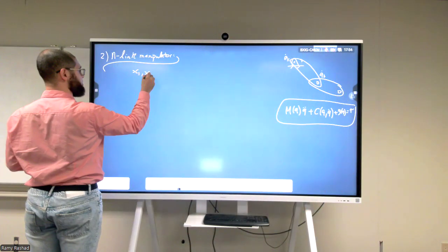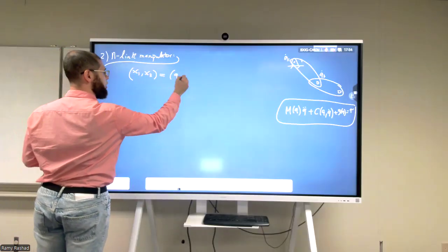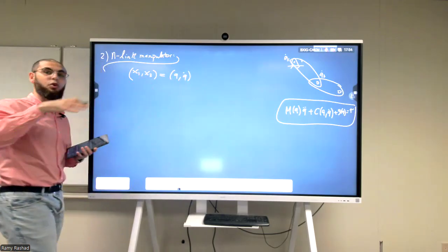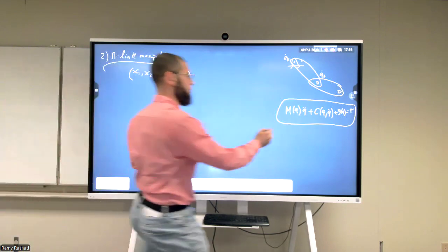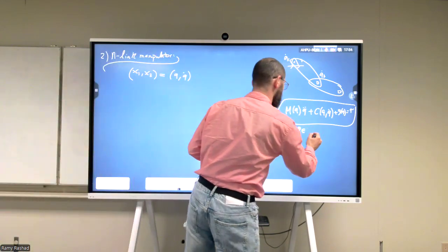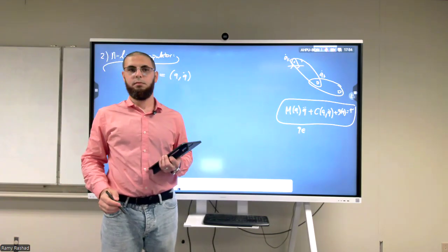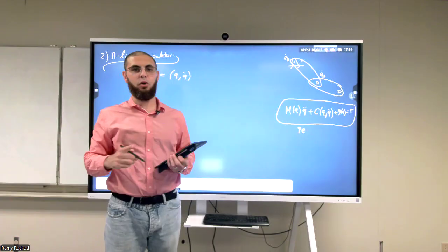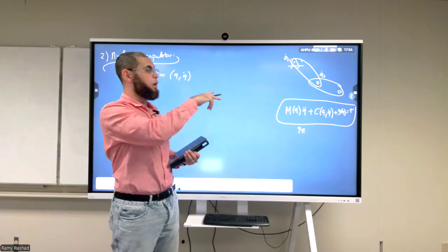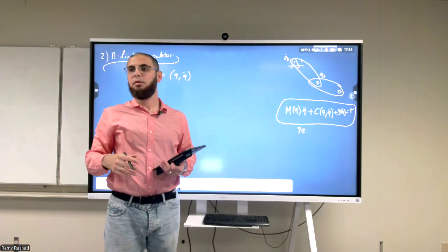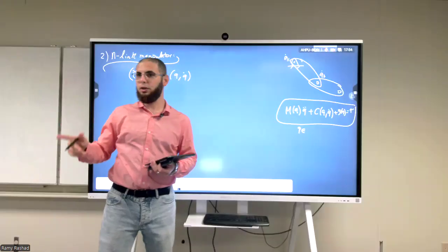So what do we choose as the state here? X1 and X2 as Q and Q dot. Where do Q and Q dot, both of them together, live? Where does Q live, for an N-link robot? If it is a two-link, or an N-link, S1 cross S1 cross... what do we call it? We call it the N-torus.